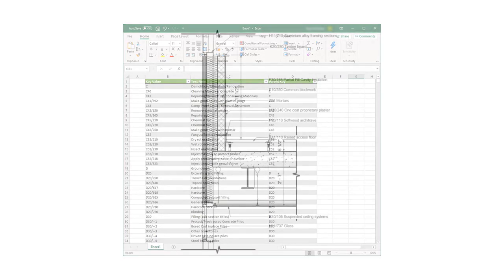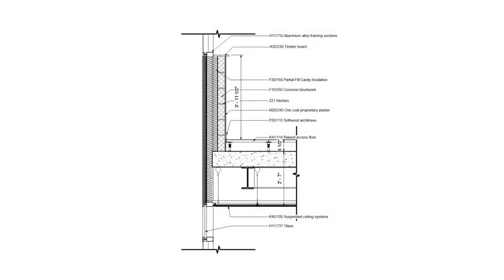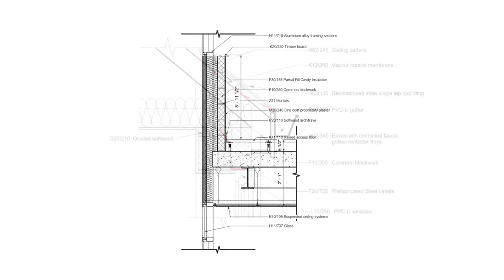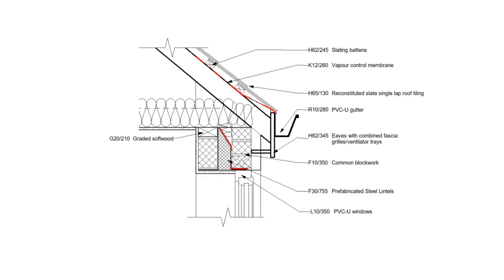Assigning keynotes and placing keynote tags on views allows us to have consistent notes for an object throughout the project, which can be changed or edited globally via the keynote parameter or by editing the keynote file directly.